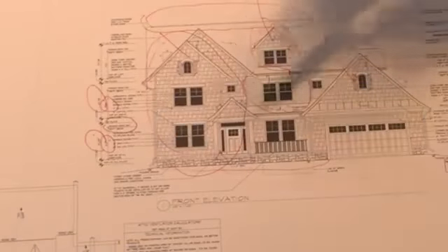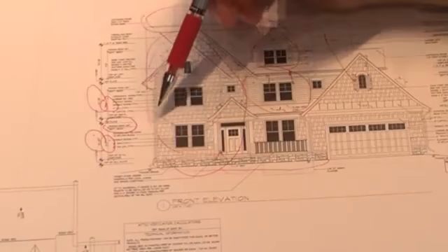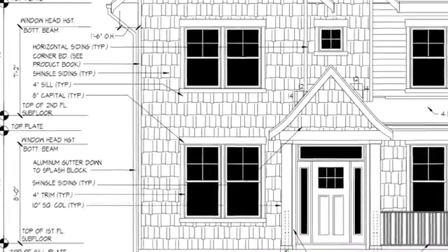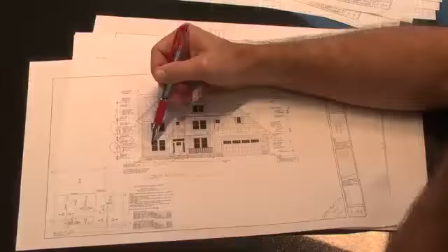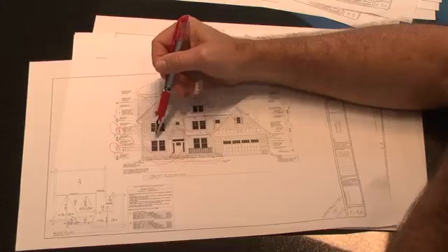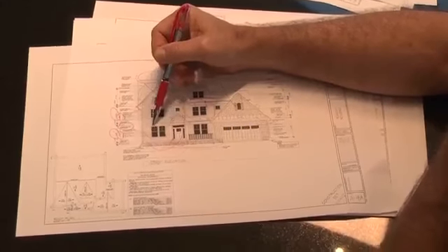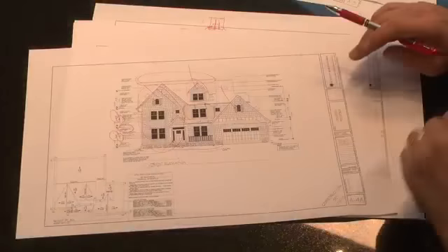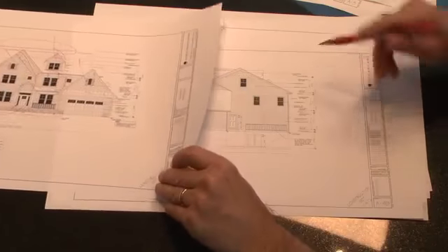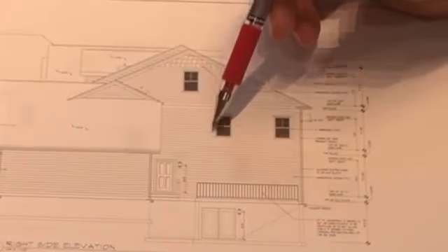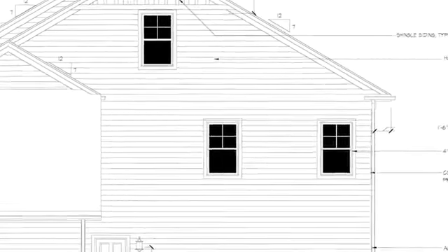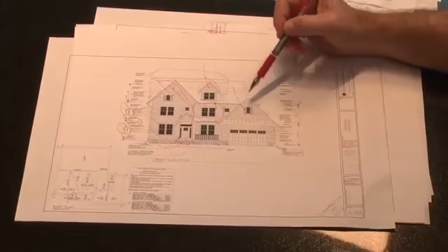A couple other things to go over with you is on the front of our homes, typically we'll do a taller head feature over the windows. So typically we'll do 4-inch vertical legs around the windows with either a 6 or 8-inch head feature, and that's just really to make the windows pop. On the side elevations, we typically will do 4-inch surrounds, so that we are picture framing the windows, but the presentation's a little bit more subtle on the sides and the rear than it is on the front elevation.